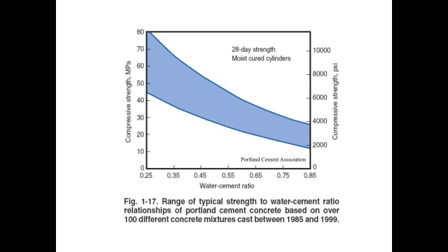Water plays an important role. Now, your admixtures do depend on the presence of water, and I'm mentioning water because I just had a student ask me this question. He's working with local aggregates, and he's having a tough time finding the right balance of coarse and fine aggregates, the right type to source. And he was starting with a very low water cement ratio, and he was having to basically max out his superplasticizer, and he was still not getting good workability. And that's very common.